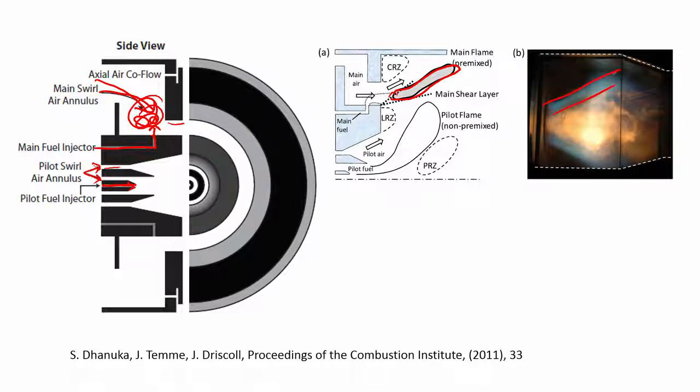This blue flame that you get is a premix flame, whereas for the central flame you do not have room for fuel-air mixing. You do not want that either, because you want a stable pilot flame inside, which is the orange-colored one, due to the soot, and that is the pilot flame.